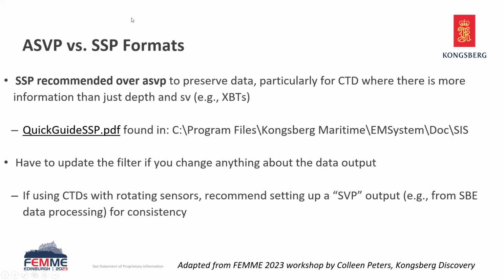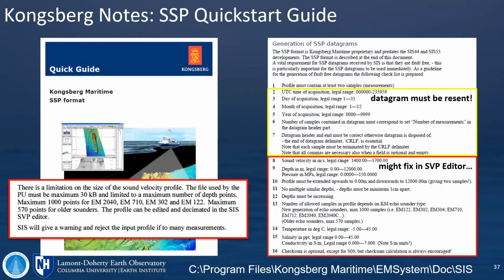There is a quick guide SSP that's available locally on your SIS machine. In there, there are some handy little tips about how to set up your SSP datagrams. We've been on trips where for some reason the sonar all of a sudden is rejecting sound speed datagrams coming across. What I liked about this quick guide is it breaks down the types of errors